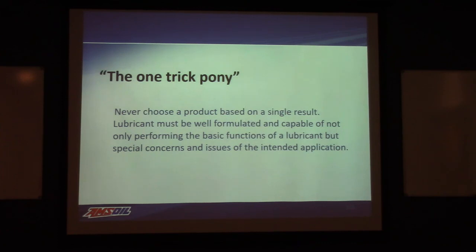You have so much anti-wear additive in there, and it's basically soaking up all the surface. The other additives can't function. It's a very, very sophisticated balance, and it can be easily altered by adding large amounts of other chemistry to it.